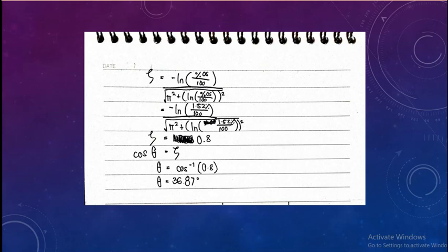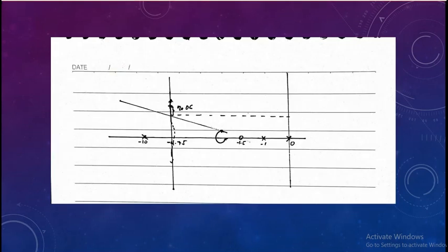With that, we can now graph our root locus with the zeros and poles. Our poles are 0, negative 1, and negative 10, while our zero is negative 1.5, while our centroid of asymptotes is negative 4.75, as discussed in the previous discussion. Now, we will use our percentage overshoot, or with the use of our theta, to graph the following data.